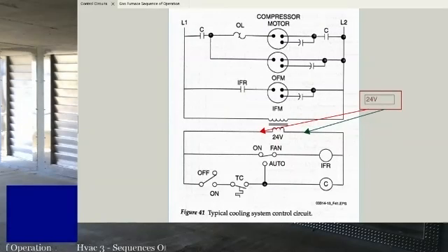Always go back and just double, triple check. Is the power wire good? Does it go from A to B? Is the breaker in good shape? It's not tripping as soon as it tries to run. Are the fuses good? You don't have anything that looks like shorts or black marks everywhere? You're keeping power at your low voltage transformer. When the low voltage transformer calls for cooling or heating or whatever, does your voltage stay at 24 volts on the terminals? It should stay at 24 volts.